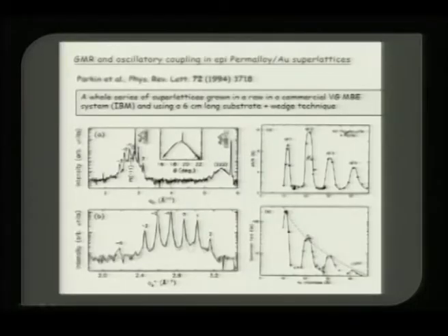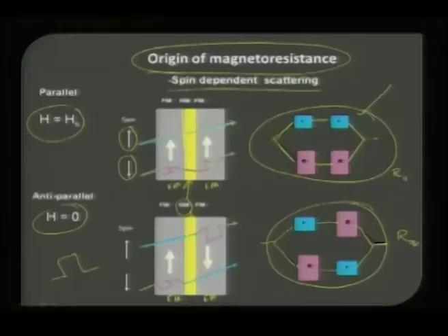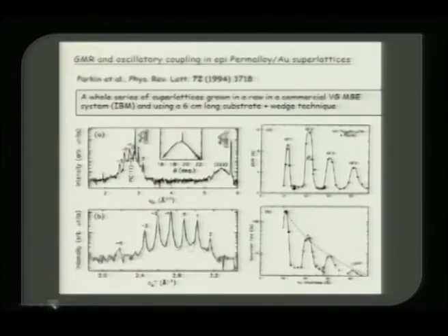One thing that we need to understand, if you want such GMR property to be there and if this is purely a spin dependent scattering, then I will come to the previous one once more. So if this has to go through without scattering, this interface has to be very sharp, there should be no roughness. If there are physical defects also, scattering will occur. Therefore you need to know how to make thin layers like this. So spin dependent scattering is one of the important issues.